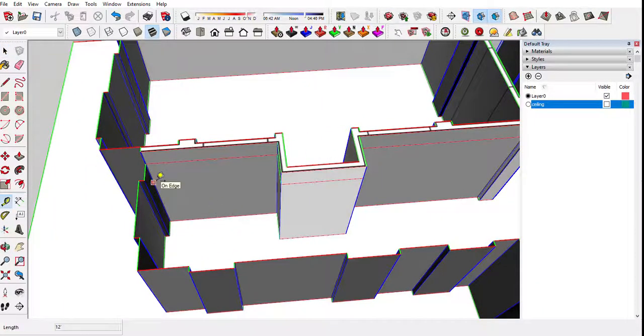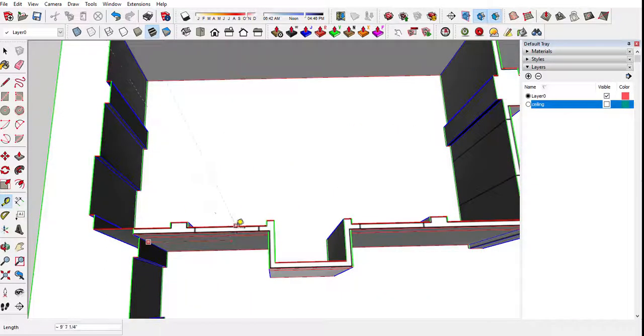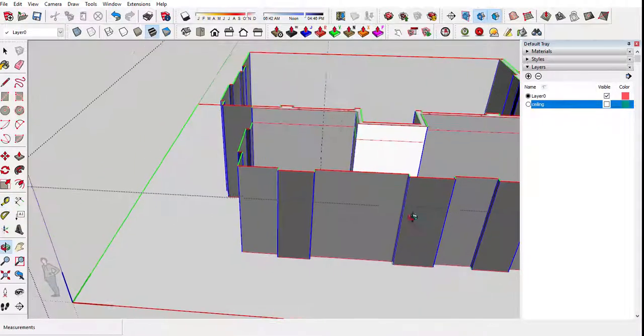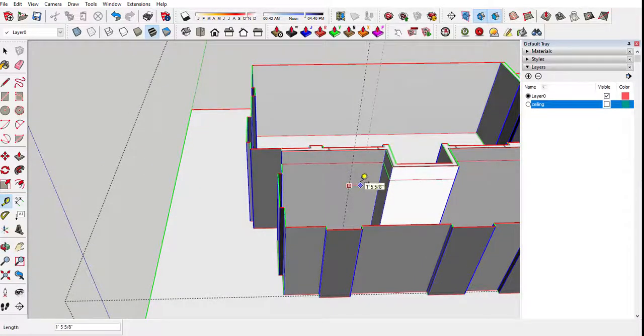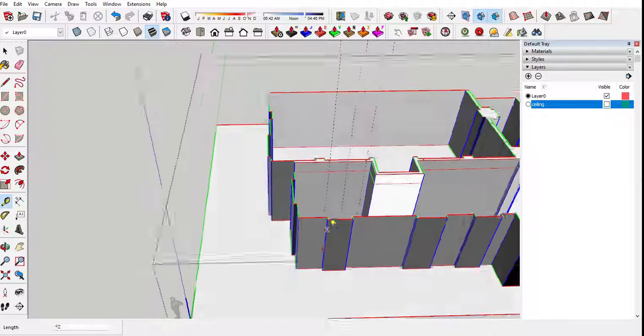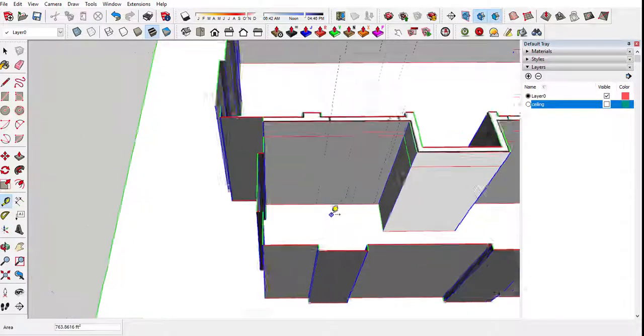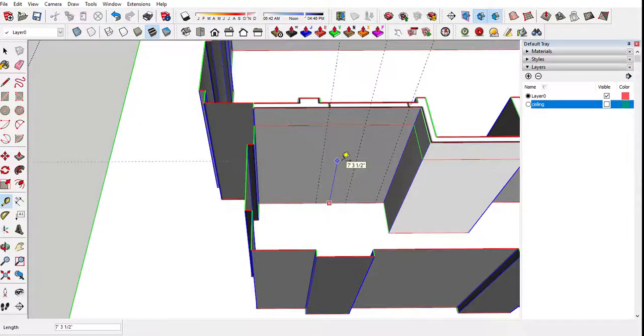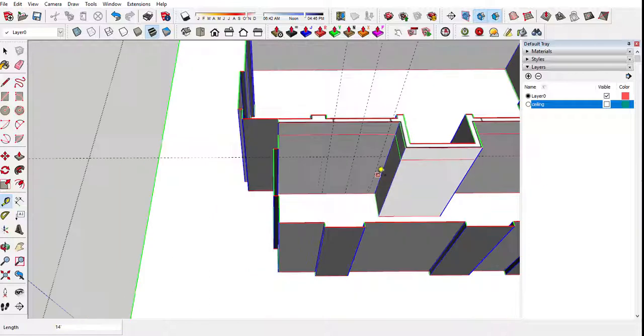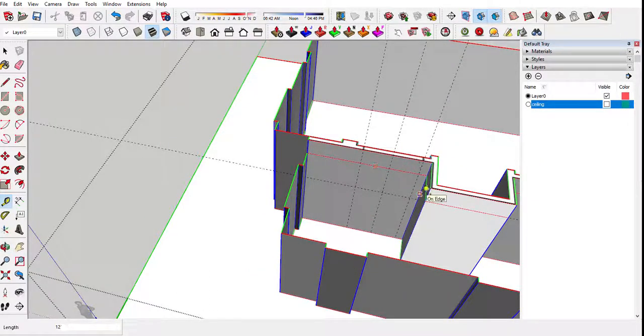I'm going to tape measure line here. So I'm going to tape measure from here to the midpoint of the back. I'm going to hit the right arrow key so it stays locked in the red. And go ahead and then go on. Then let's do 36 on this side, 36 on this side. This will give us the width of a 6-foot door. And then we're going to go up, I think maybe 8 foot in the blue. Because it's a larger room, it probably has a larger door. It might even have an archway on top or a large transom or a nice panel design.